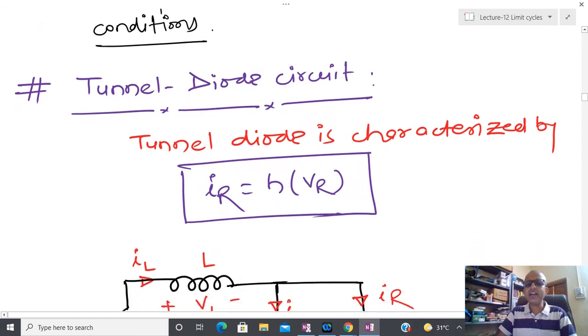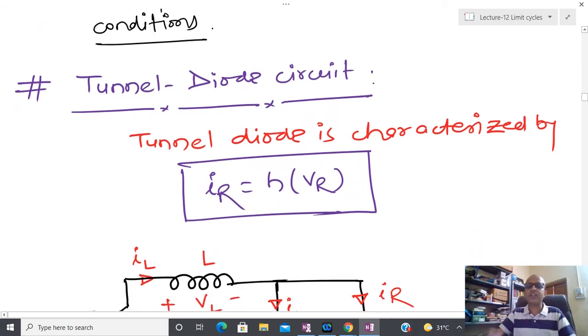Okay, and I'm not going deep into how to construct a tunnel diode. If you have interest, then please look through Wikipedia. But I'm just going to understand the tunnel diode in the form of some kind of mathematical modeling. So what is the beauty of the tunnel diode? If you see the IV characteristic, you can see from this expression that it is not like Ohm's law. In Ohm's law, if we increase the voltage, then current also increases, and after that some linear relation is there.